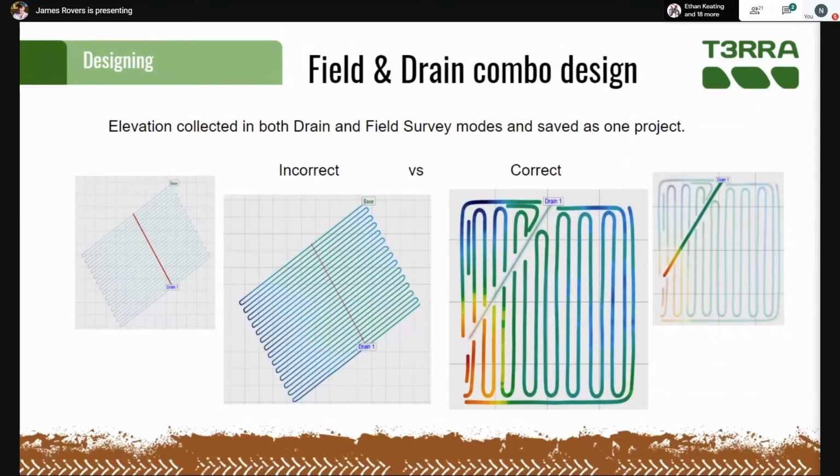If you are going to balance the dirt in a project which contains both a field design and a drain design, then best practice when you are collecting data is to pause when traveling over the drain area. Best practice is to not replicate points by collecting a drain survey driving over a field survey. If a surface and drain exist as one project, the surface must be designed first and the drains designed second. If you decide to go back and alter the surface design, be sure and redesign the drains again as well.